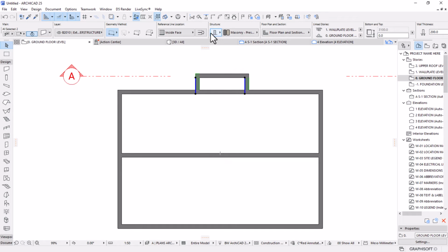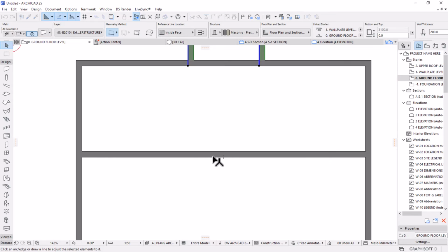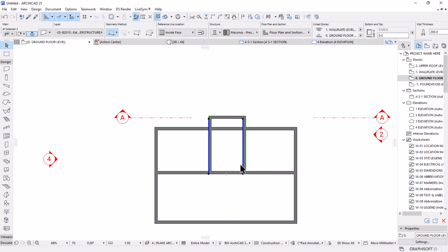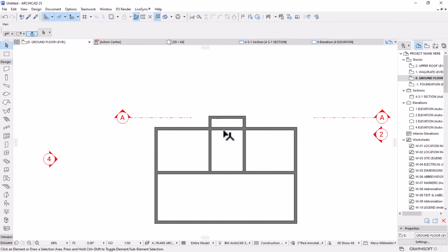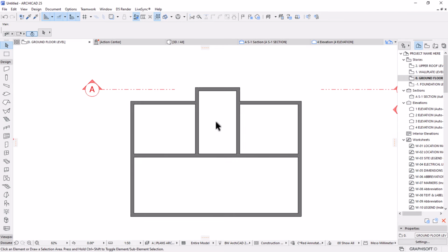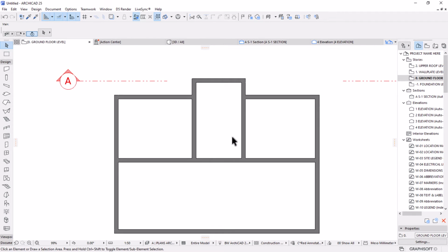And then these two walls have to go all the way to meet or intersect with this. So I'm going to use a tool called intersect, which is at the top of your interface. Activate it, then come here and click on your wall. It will automatically adjust those two walls to that area, and then I can get rid of this wall by activating the trim tool, or hold Control on your keyboard to activate this tool and then click on the element just like that.